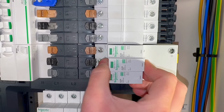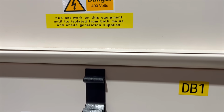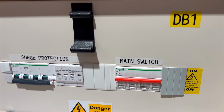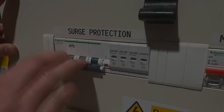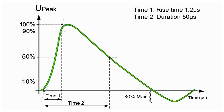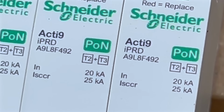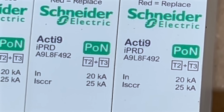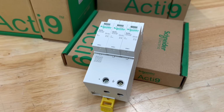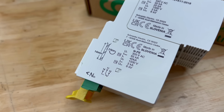A type 2 SPD is intended to discharge the main surge currents associated with indirect lightning effects and switching events. It is typically installed at the origin of the distribution board and is tested using the 8/20 microsecond waveform defined in BS EN 61643. A type 3 SPD has a lower discharge capability but provides a lower voltage protection level. In a combined type 2 and type 3 device, both stages are coordinated within one assembly. The type 2 section deals with the surge current. The type 3 section reduces the remaining voltage seen by equipment connected to that board.